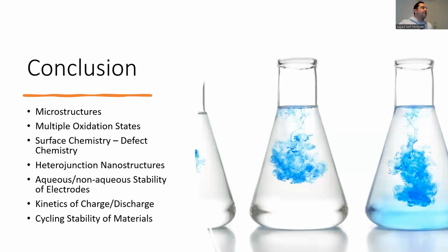Because pseudocapacitance is all based on redox reactions, choosing materials that have multiple oxidation states is suitable for these applications.